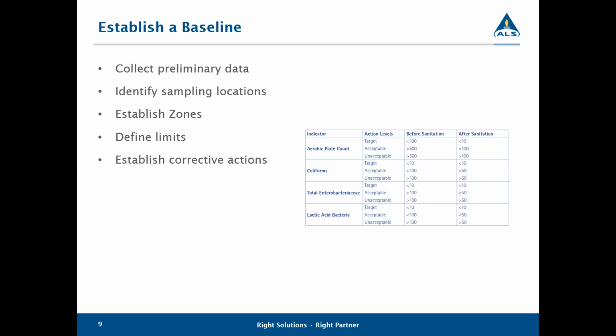You may not know exactly where it is, but you don't want to track it anywhere else into your facility. So you want to break down and inspect your equipment in the area, re-swab the positive area and the surroundings to determine if contamination has been localized or if it's spread somewhere.